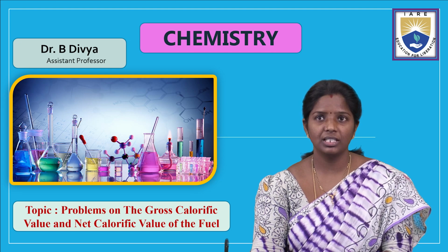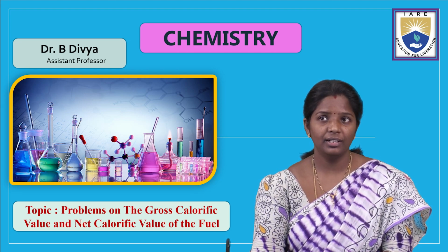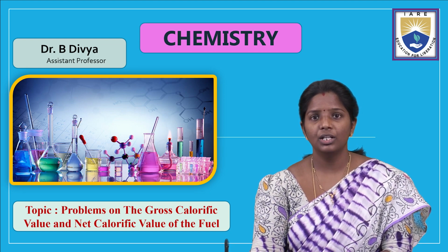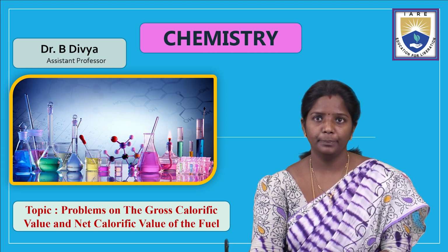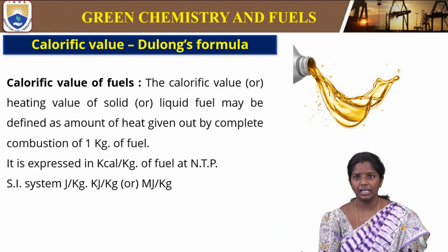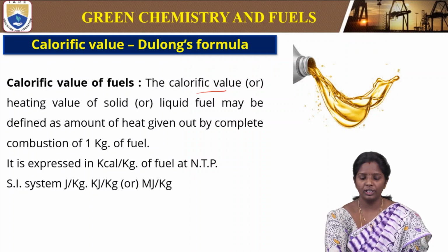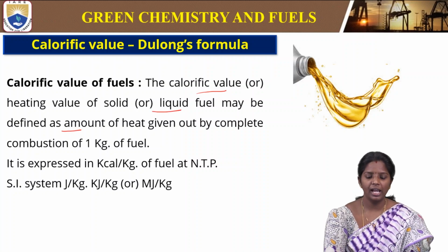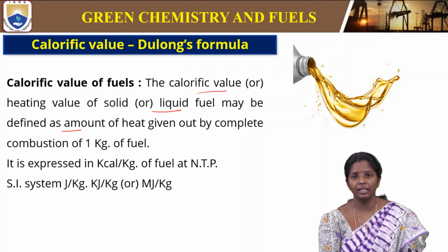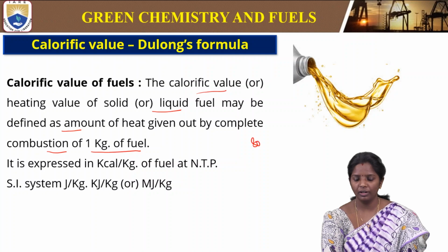So in this session, we will discuss the numerical problems on gross calorific value and net calorific value of any fuel so that it can be selected accordingly. Before going to that, we should know what this calorific value is. The calorific value or the heating value of a solid or liquid fuel may be defined as the amount of heat given out by complete combustion of 1 kg of fuel, whether it is solid or liquid.